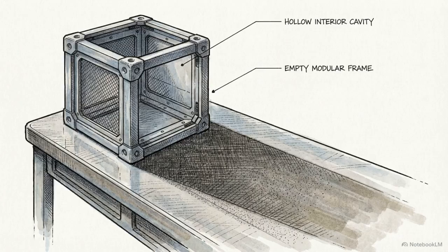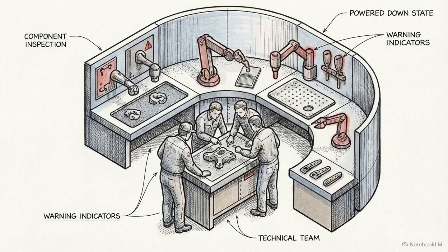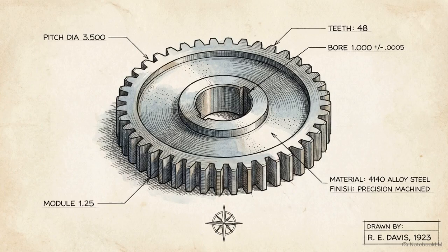This exposes the factory to the constant, looming threat of a complete stockout because the company no longer maintains inventory buffers. That exact risk is what enforces rigid quality control. Because there are no extra parts, a single defect will immediately halt the entire production line, forcing the team to solve the problem instantly. JIT forces higher quality not through better inspections, but by removing the safety net of excess inventory. The focus shifts entirely towards zero-defect prevention.